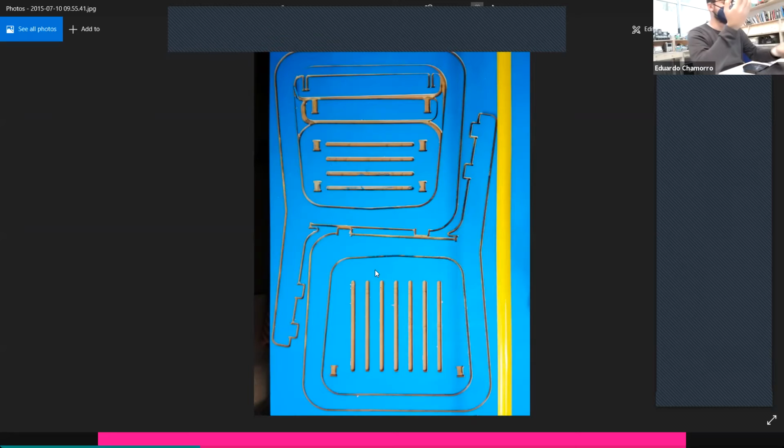Why? Let's say we have cut this, and then we come back and get introduced into here. What is happening? The material has moved a little bit, just a little bit, enough to hit the end mill at really high speed. Again, you will damage all the side of your cut if you already cut in the same spot. You can make it happen.